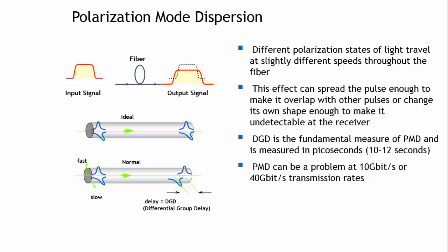So when we plan our optical transmission network, we need to see what the data rate is against the accumulated polarization mode dispersion before it gets compensated. This is basically measured in terms of differential group delay between polarization states.